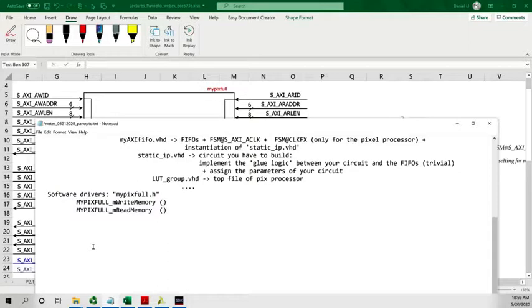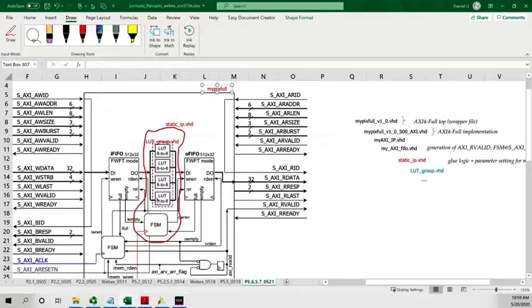I think there is one more, but those are the two most important ones that you can use. Because how do you communicate with this peripheral? You have to write on a particular position in memory and read from a particular position in memory. In this particular FIFO configuration, there is no need for you to specify a memory position. Any of the 16 words where you plan to write will work as well. That's why we have 6 bits here for the memory. So you don't need to do anything. You can write on any position or address and it will work the same. We will see later that it is possible to decode particular memory positions such that you do specific instructions, but that's later, not for now.